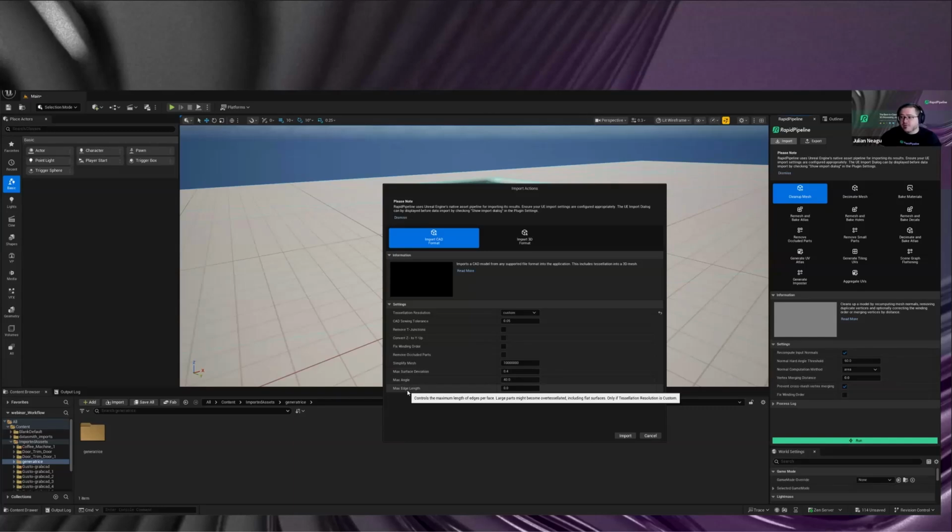As tends to happen in a tessellator, those surfaces tend to be populated with very long, thin triangles, depending on the curvature, where you have holes and features with a lot of vertices that you have to connect to, and to avoid n-gons and so on, you will have thousands of triangles there. But with the max edge length feature, you can say, hey, these triangles consist of edges and they have a limited allowed length, meaning that you can basically place almost like edge loops in the middle, in the best case for the tessellation, and decrease the length of these features.